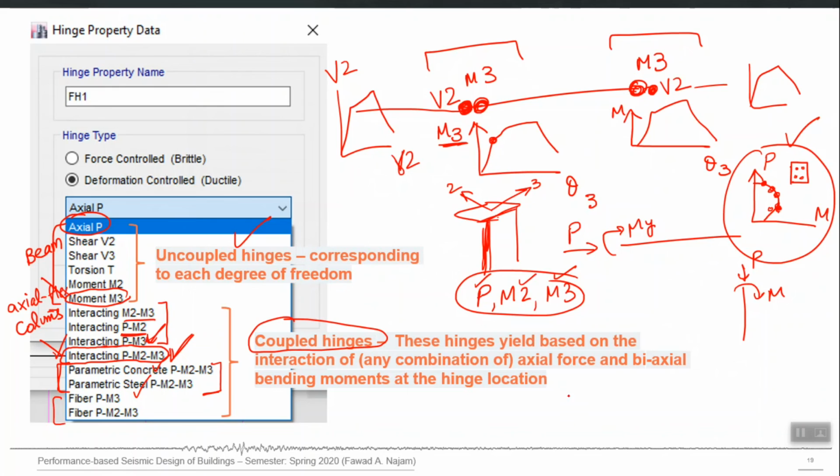If you define a relationship between the plastic rotation of a beam theta and the shear capacity Vn of a beam, for low levels of theta it will remain constant, but for high levels of theta it will reduce to a very low number, because it is obvious that when the beam is close to failure in flexure, the shear capacity is no more constant because of the reduced cross section and because of all the other flexural deformations or deteriorations, right?